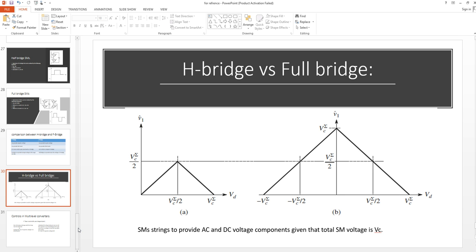We basically concluded that HVDC has a number of advantages as compared to HVAC, and then we discussed two level converters, and what multi-level topologies were used in the past, like the diode clamped converter and the flying capacitors converter.